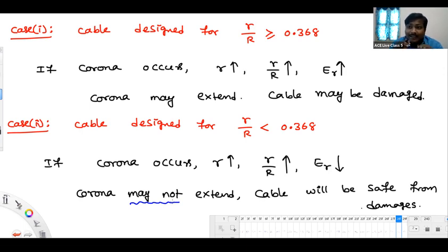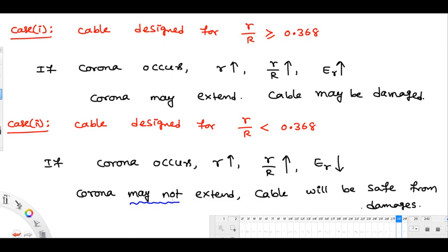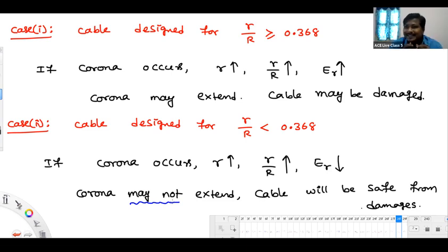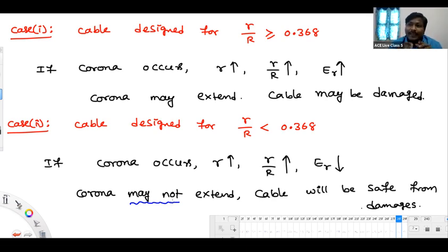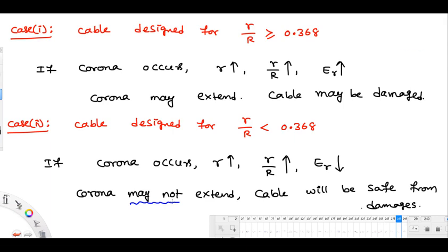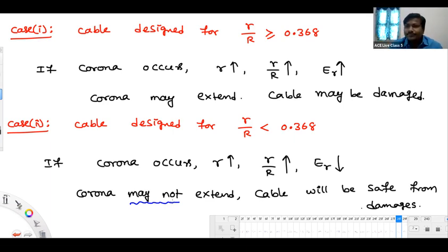But 3 conductors are causing that, na? Phase A, phase B, phase C. That net interference may be less. Okay, sir. Because of this little cancellation. Okay, because they are 120-degree phase shifted from each other. Yeah. But if you are using a 3-core cable, that issue may not come, because outgoing flux itself is 0, right? Yes, sir. The sum of the 3 fluxes will come 0. Outgoing flux is 0. So we may not get that interference if we are using a 3-core cable.